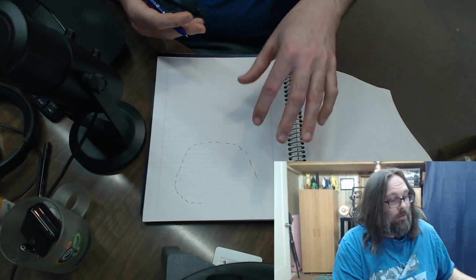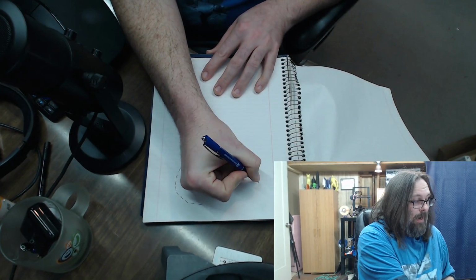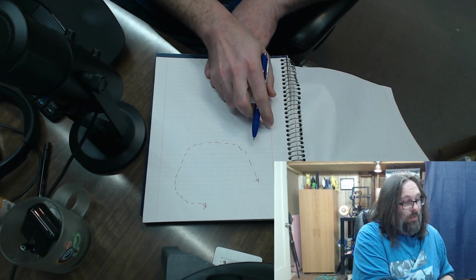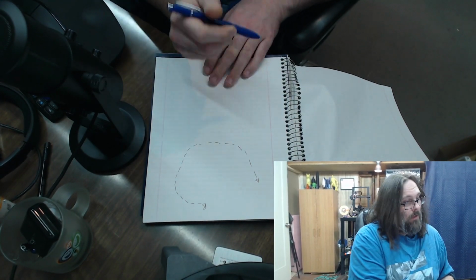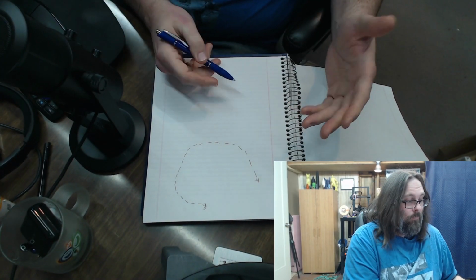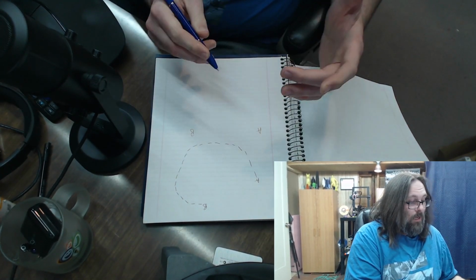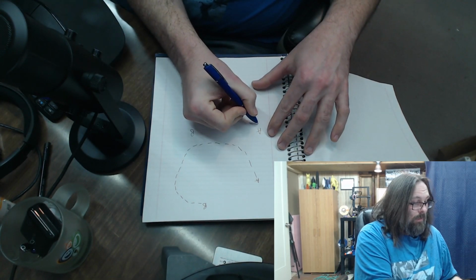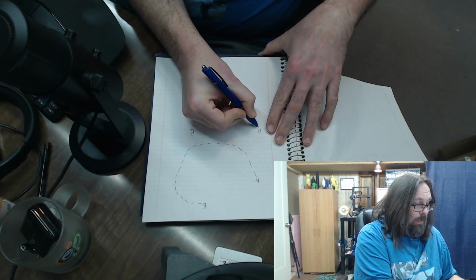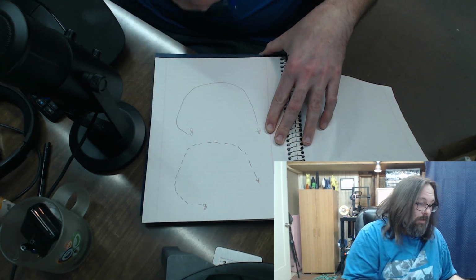What Arc Welder does is it converts these straight lines into a curve. So if we start at point A and we want to get to point B in our slicer, this is what we're doing right now. And this causes extrusion start, stop, and lots of stutter movement. So it's not the smoothest way to actually get a good print. So if we start at point A, and again I want to get to point B, if I'm using Arc Welder, instead of these dashed lines, the slicer in a post-processing script will say, oh, well, I can just connect all these segments now. And it will literally do this and draw a nice line right back to B.